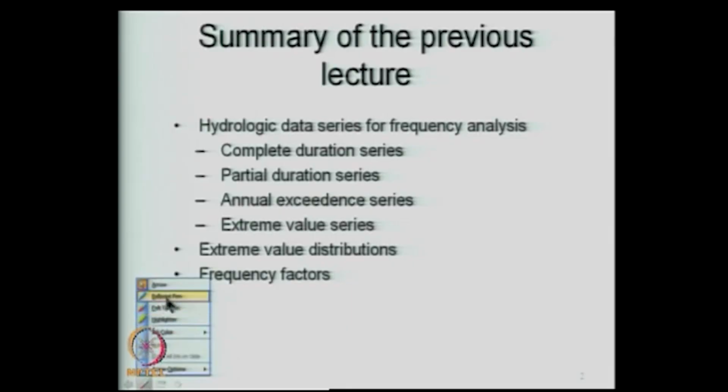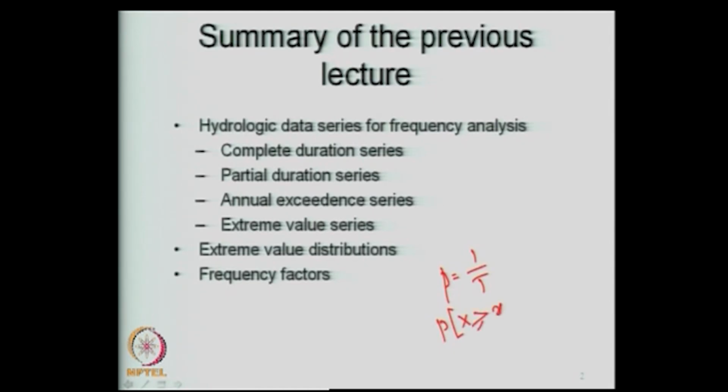So, typically we are interested in that particular magnitude, flood magnitude typically, which will be exceeded once in about 20 years, once in 50 years, once in 100 years, etc. So, this is the concept of the return period, and we recall that the return period determines the probability. We have shown earlier that probability is equal to 1 by T, where probability is the probability of x being greater than or equal to x_T, and x_T is that particular magnitude.